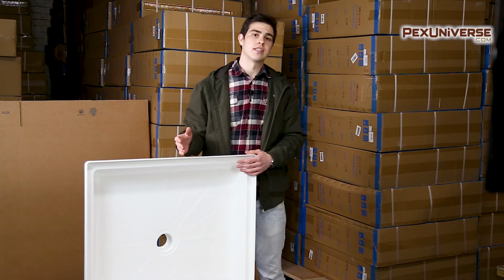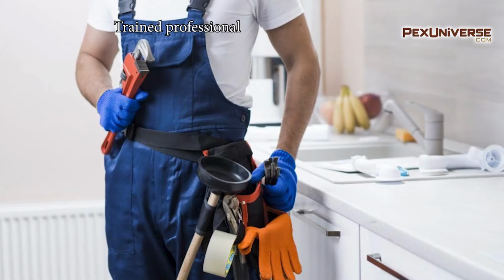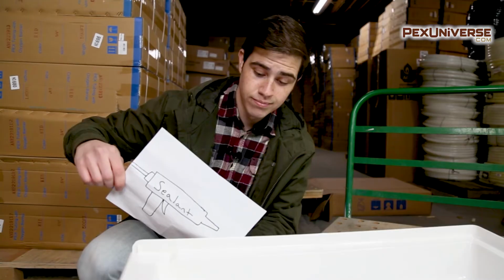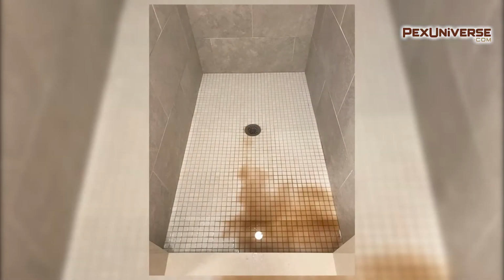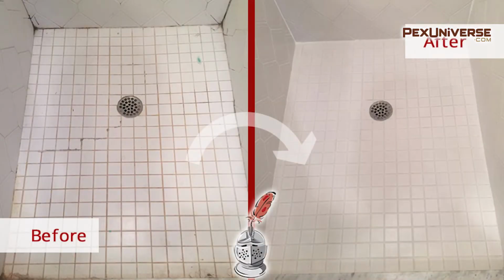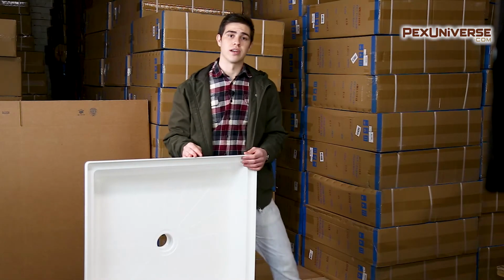If you do choose to go with tile, there are some other things that you're going to want to think about. For instance, you will want a reputable professional to install it. There's a lot of leveling, sealing, and attention to detail involved. After it's installed, hopefully correctly without drainage problems like stagnant water leading to mold, you'll still have to maintain the grout between the tiles more often. Tile is an awesome option if you execute it correctly.